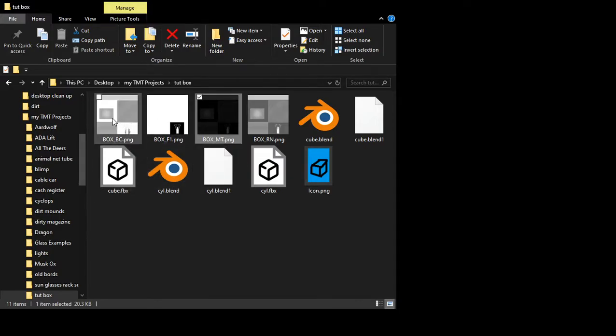Anyway, so we got our base color, our flexi, so we could change the base color, which you want to make albedo, which means it doesn't have any shading applied to it. It should be all grayscale, so no blacks and no solid whites. This particular one was made for a light bulb that used alpha blending, so that's why there's a white area, and that's because those areas weren't being flexi colored. But for this object, I'm just trying to get it in game, so I don't really care what the texture looks like. I just need a basic texture that'll apply to the object.